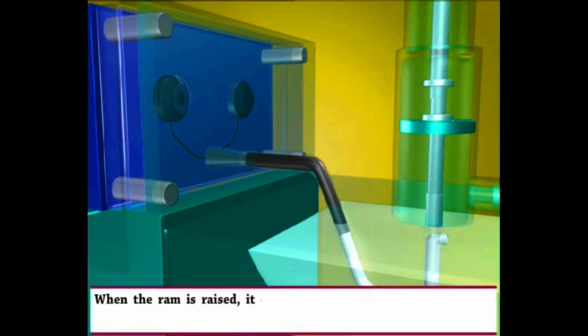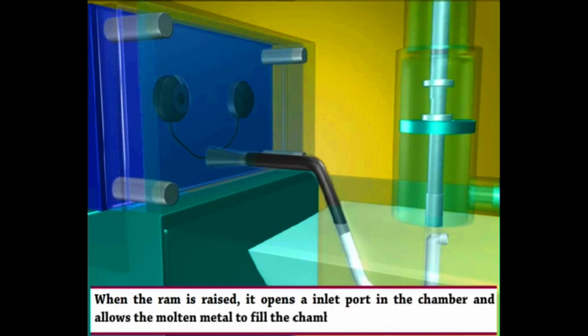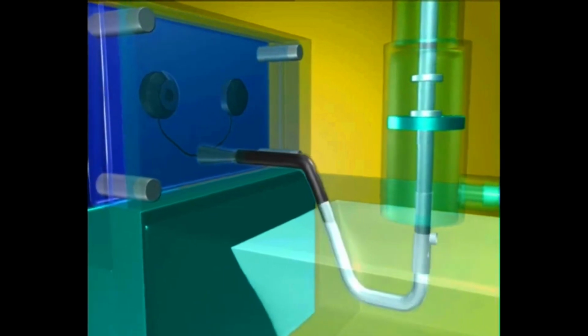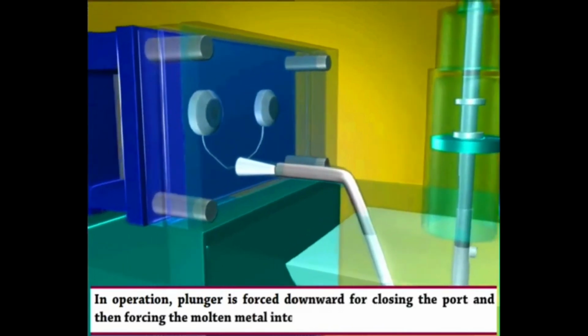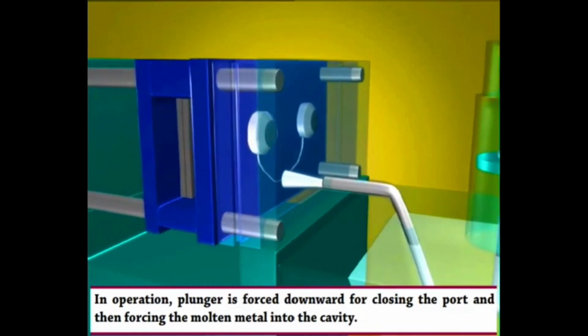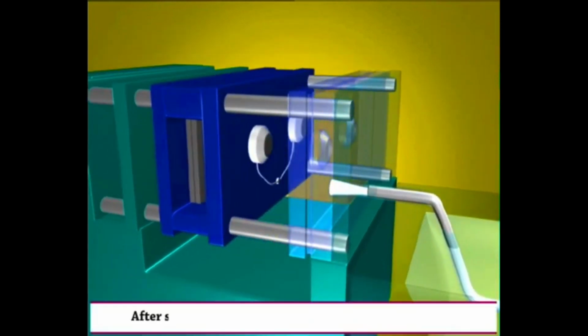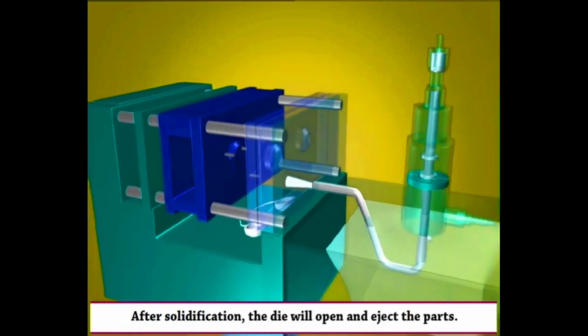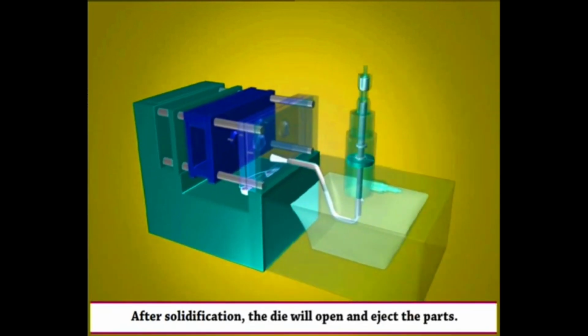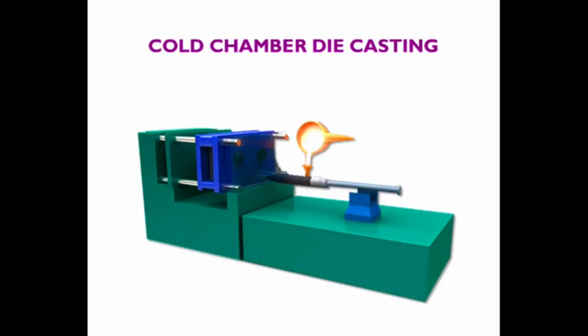When the ram is raised, it opens the inlet port in the chamber and allows the molten metal to fill the chamber. In operation, the plunger is forced downward for closing the port and then forces the molten metal into the cavity. After solidification, the die will open and eject the parts.